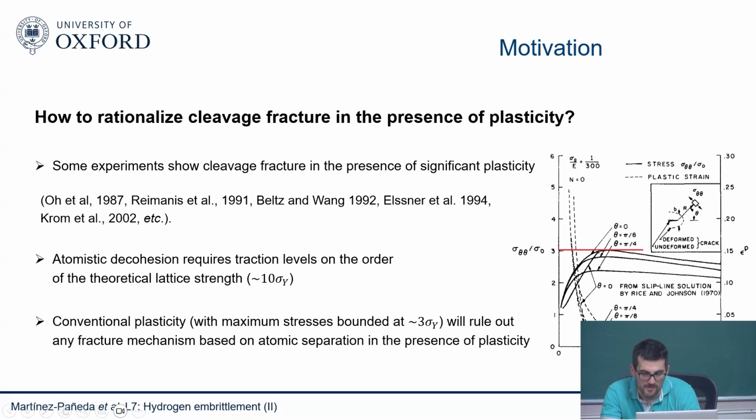So this is the very first finite element paper on large strain plasticity, looking at crack tips. This was done by McMeeking in the 70s. He was a student of Jim Rice at Brown back then. What he's plotting here, the solid lines, are the crack tip stresses, normalized: the hoop stress, so the stresses ahead of the crack tip.